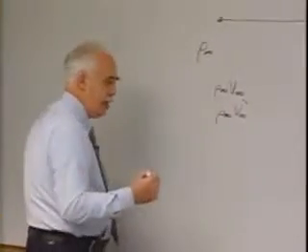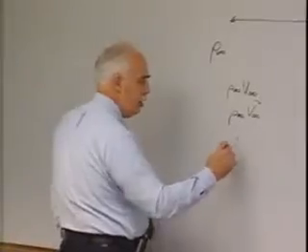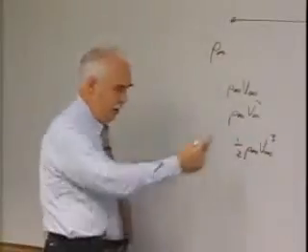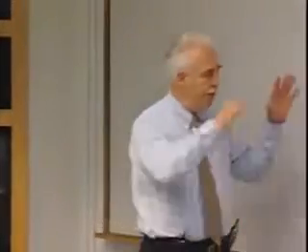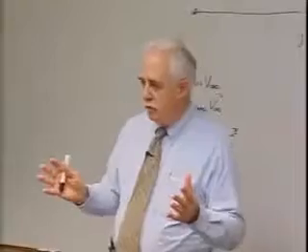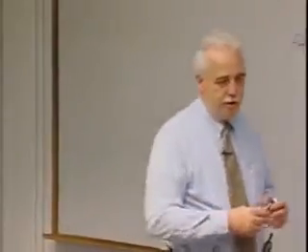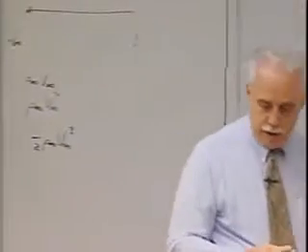The energy that the gas has relative to you is 1/2 v squared, and so we're looking at an energy flux on the order coming to the vehicle 1/2 rho v cubed. Those are very important parameters, and people have gotten lost. I'm going to focus on accuracy and not on precision. People have gotten lost in details in terms of getting parameters. If you've got density and velocity, you basically have the gas parameters, with some major exceptions, which I will get into. The other aspect, and that is relative to the equation of state, if you want, the constitutive relations. The other thing is the geometry, which is the major difference between the Apollo and the Shuttle.